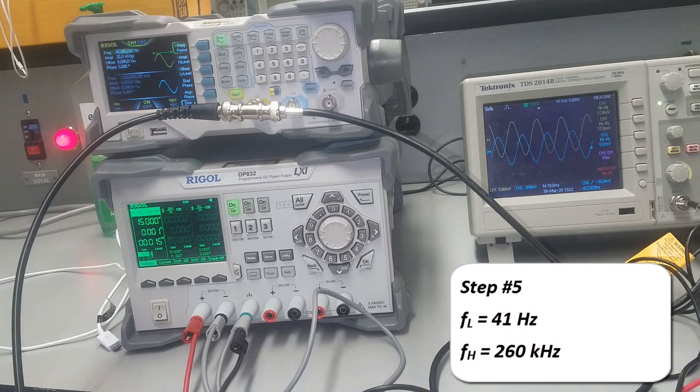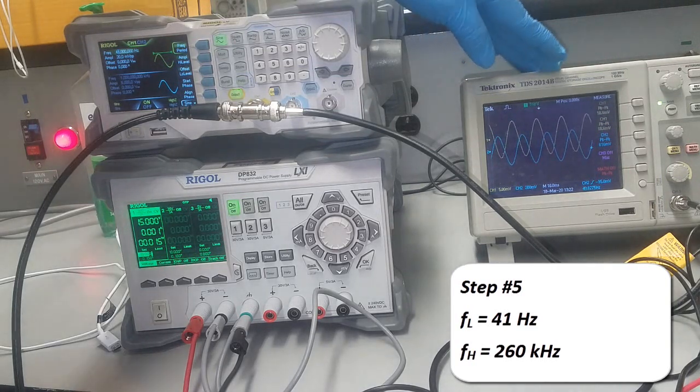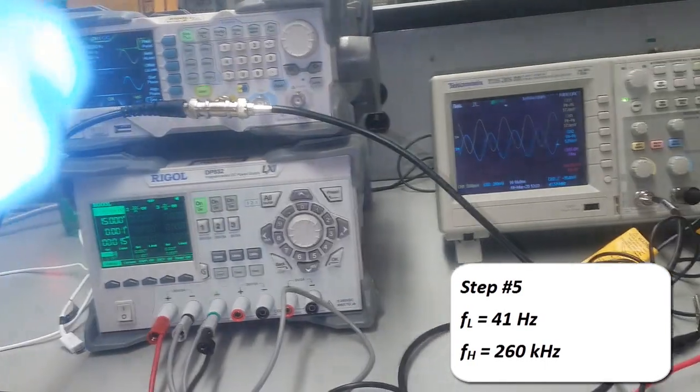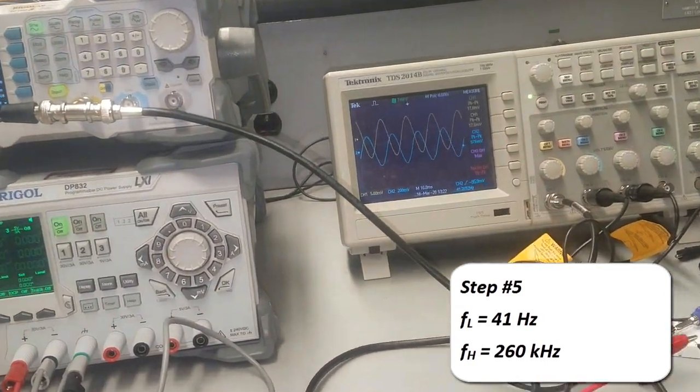Now I'm using the average here because the signal is noisy, but sometimes when we get a noisy signal from the scope, we're going to fluctuate between acquire and measure, because acquire basically will make us trigger. Instead of averaging, we can trigger. So let me zoom in on the scope to show you how we can do that.